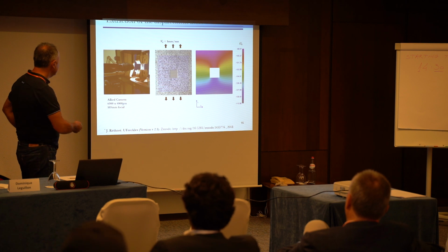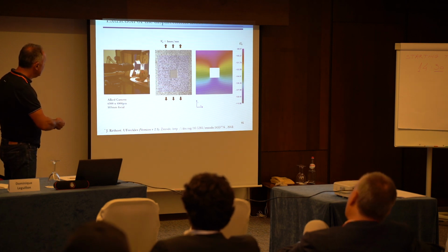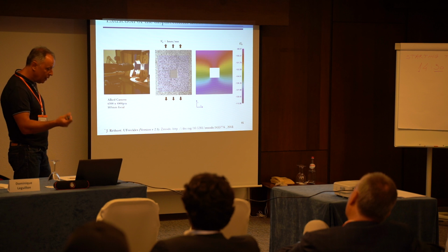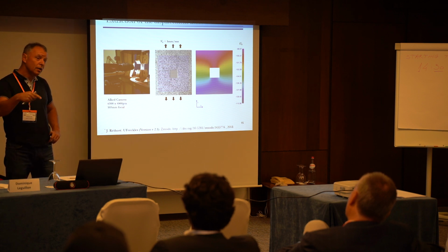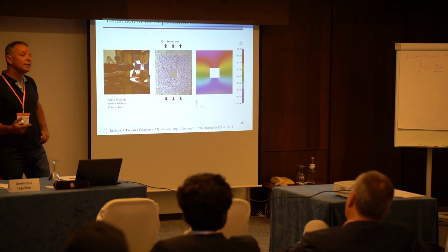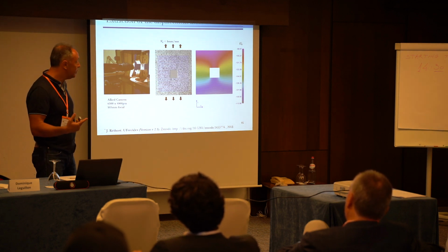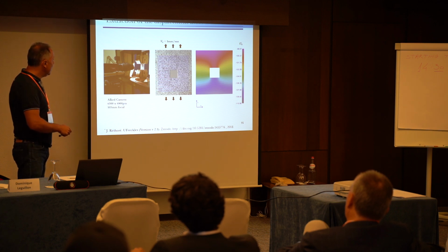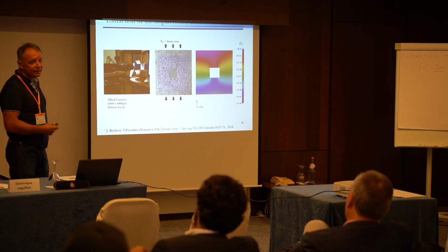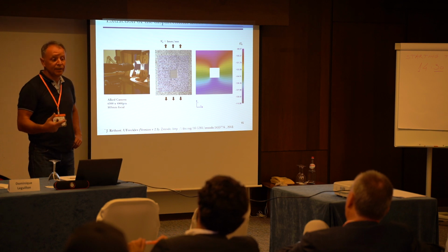Then you do an experiment. It's very simple: a test machine, a plate of PMMA with a square hole. We cut the PMMA, then we perform a heat treatment to remove potential stresses that came with the machining process. This is supposed to be a neat plate of PMMA, at least free of initial stresses.